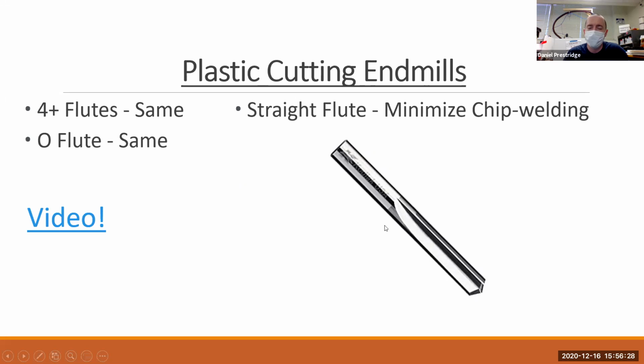Again, the surface finish leaves a little bit to be desired, but for at least a lot of the cuts that we do, it's not as important as actually getting something on there and figuring out if it's going to work or not. And then you can go back and run these things called finishing passes, where you would clear it and then come back either with a different end mill, or with the same end mill, go slower, or take less of a depth of cut so you don't have all of those vibrations and issues that you'd run into.